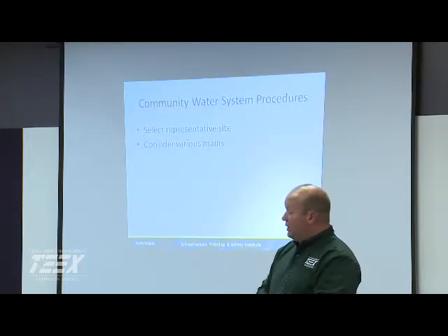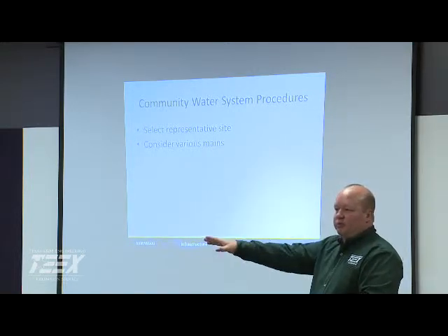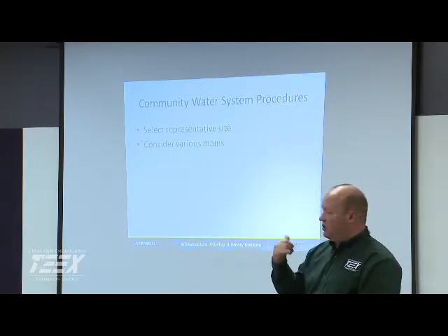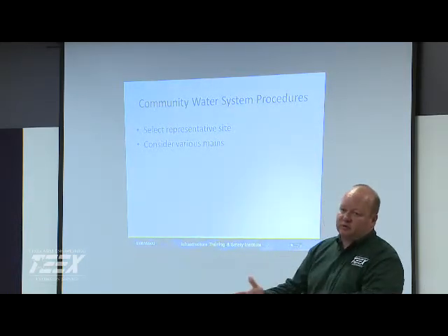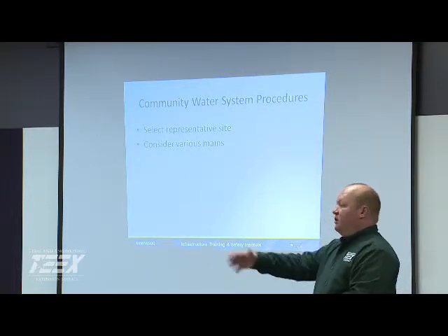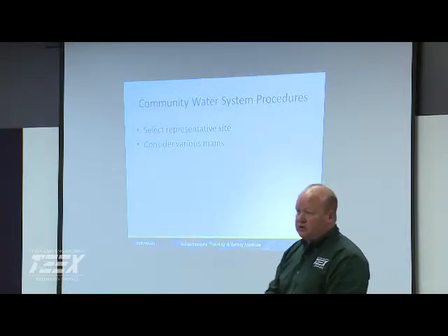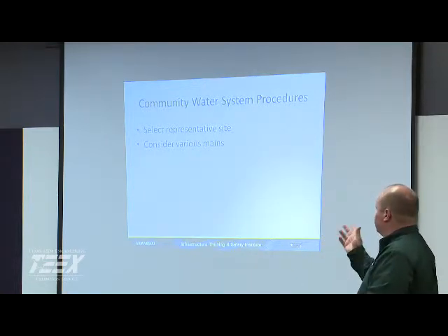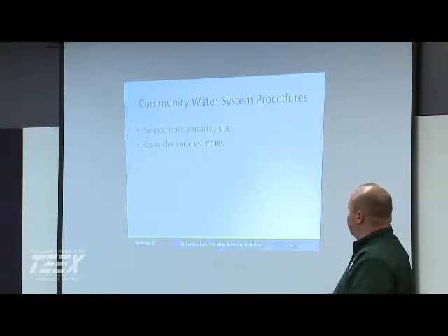Yeah, I understand. It is about how many people it's gonna take to do something, how much time you're gonna tie up. But there's also that component of, if I don't do my PMs properly, what's it gonna cost me? That's a big issue when we get into, like on the distribution system, your pumps and motors and all. If you're not maintaining them properly, if you don't have some sort of a preventative maintenance program, you have catastrophic failure, now you're really up the creek trying to scramble and get stuff going again. And it would normally cost you more in the long run by not having a good program. So those are just some things that, from my experience, have been beneficial.